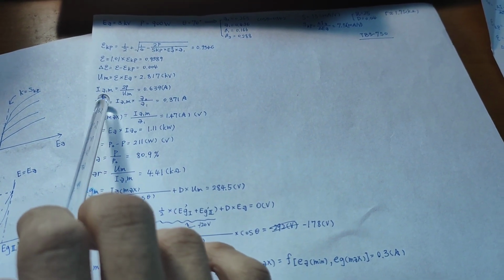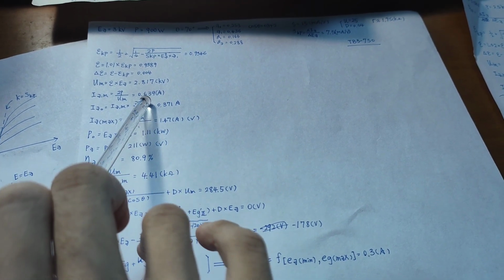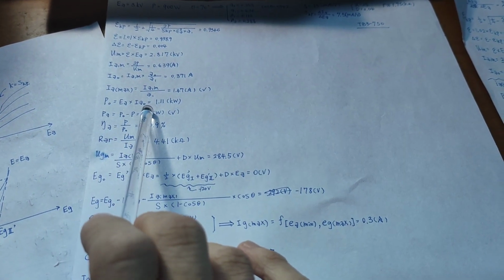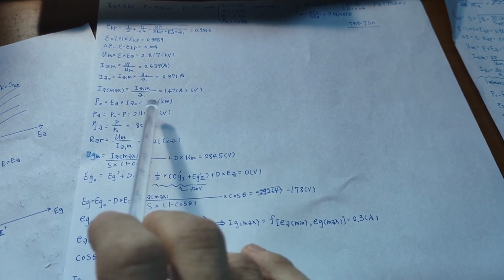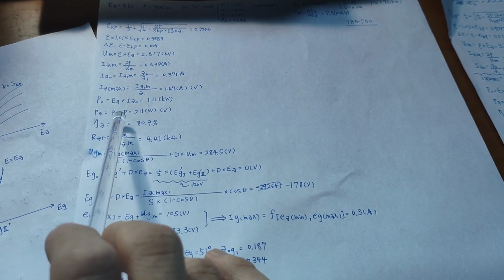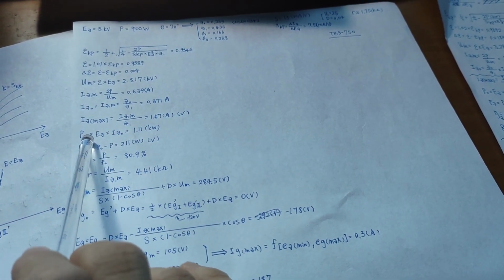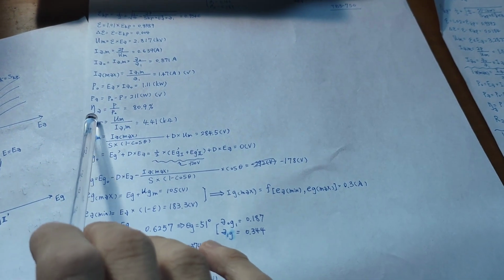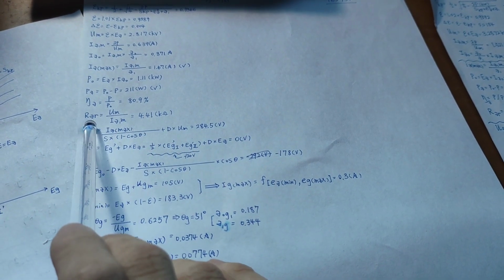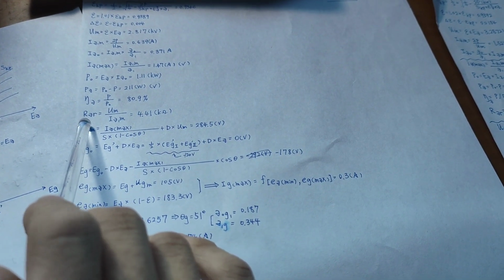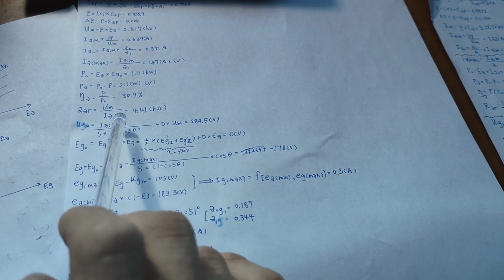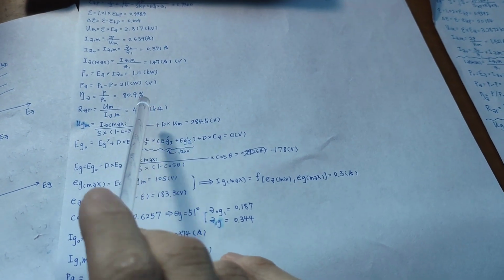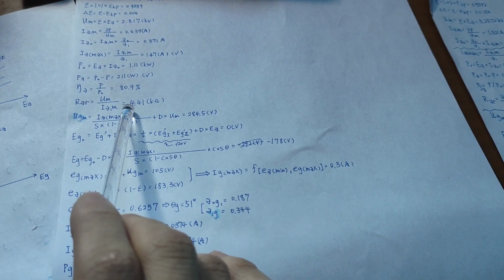This is just a harmonic current of the anode waveform, and this will be the maximum current, and this will be your anode input power. You can calculate it, and you can calculate the anode dissipation by just doing a subtraction between this one and your rated power. So also this is a safe value for my tube, and you can calculate the efficiency if you want to. And this is the load resistance when your anode is in resonance, and this you can calculate. This is a rather important value because this will determine how well your load is matched to your oscillator.